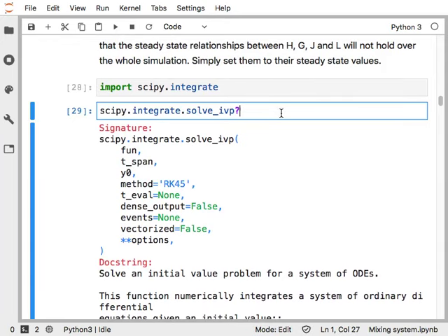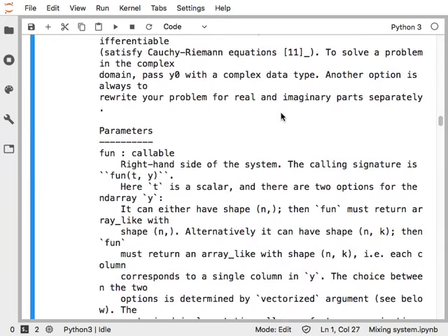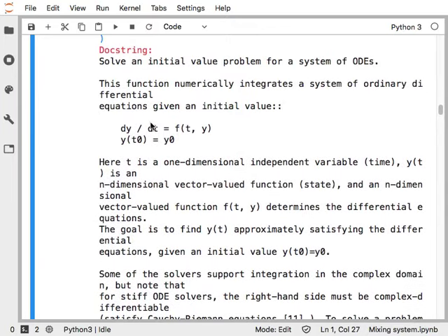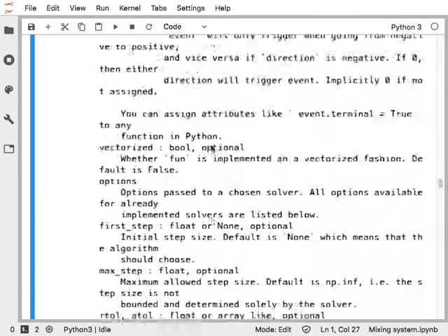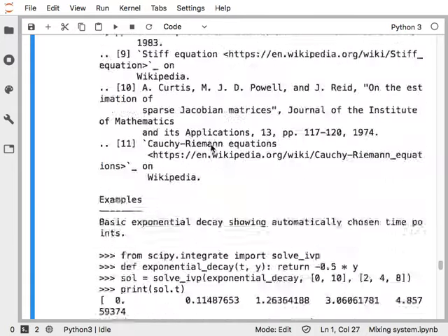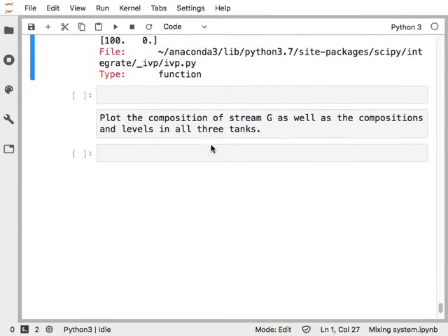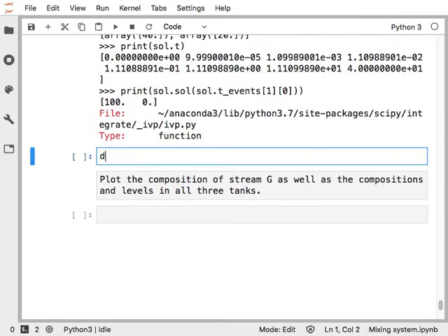Okay, so we're going to use solve_ivp. But I want to actually understand what it is that this function is supposed to return. So this function is supposed to return the derivatives of the state. And so if we're talking about only solving the mass balance for now, there are exactly 3 natural states that we have to take into account, right? Which is the mass in each one of these different tanks. So I'm going to write a function that enables me to calculate that mass, or that mass derivative, okay? So my target is to get to something where I'm able to do this.